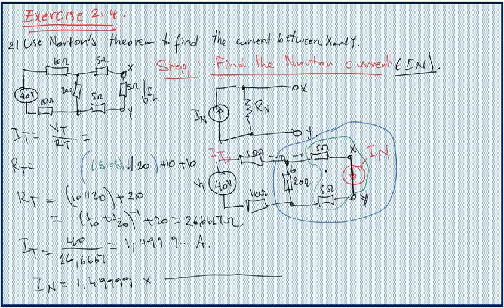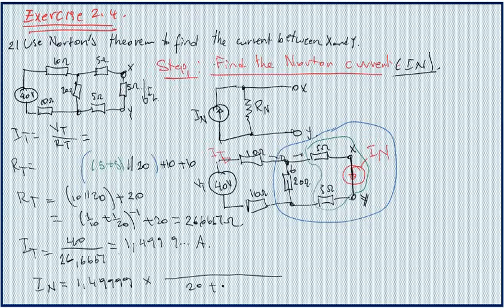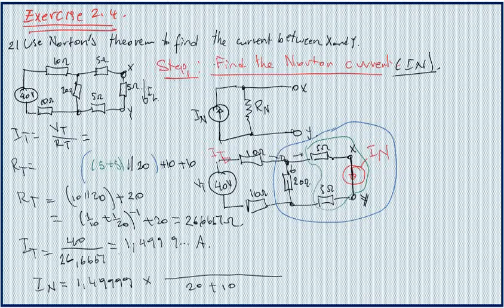So we have two resistors that are in parallel. So at the bottom I'll first need to add them. So I have 20, and the value of this resistor is 10. And on top, because I'm calculating the current flowing in this resistor, I'm going to need to use the opposite resistor, which is 20 ohm. So I need to put my 20 on top.